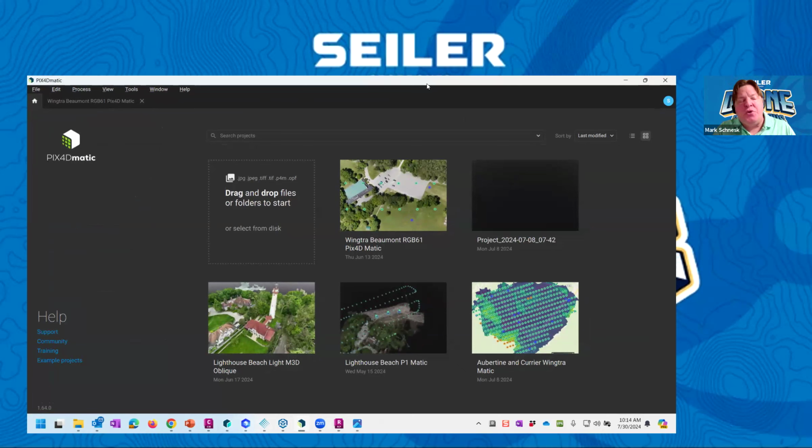But just to show you, no matter what software you use for processing photogrammetry, it's basically handled the same way. We're going to import that data in. The software is going to read the XY position of each photo and arrange them in a matrix within real-world coordinates. We're going to calibrate those images. It creates a lightweight model based upon the 3D stereoscopic mesh it sees. Then we're going to say, okay, this is good.